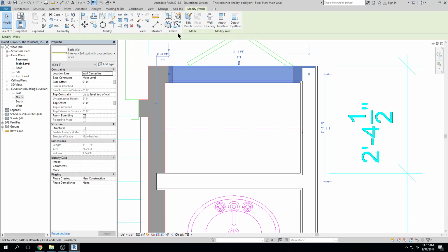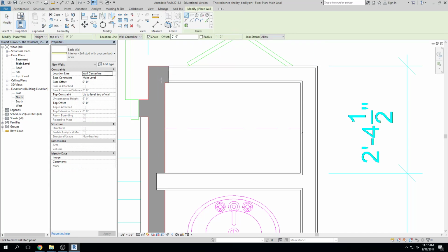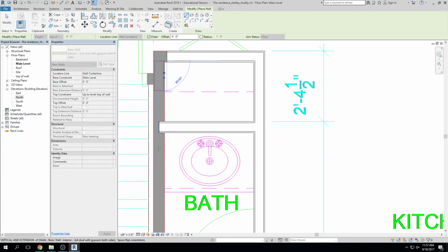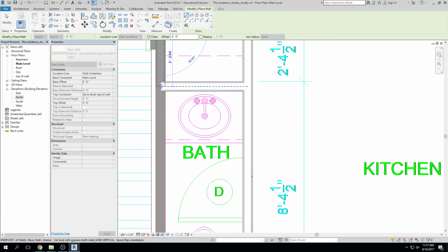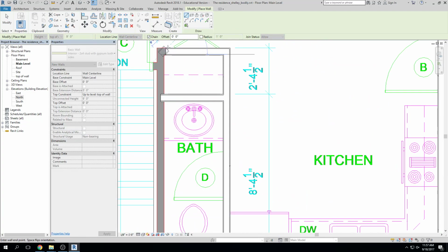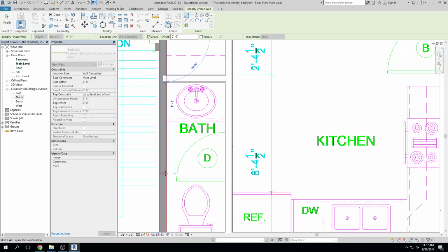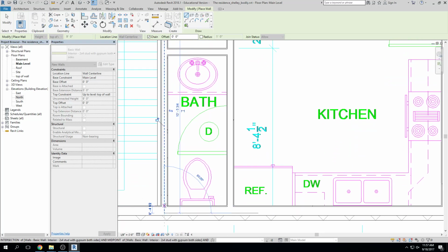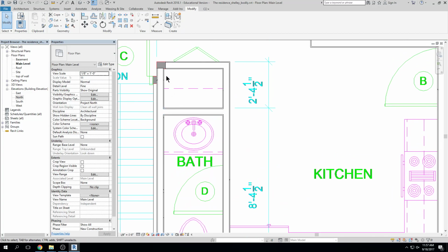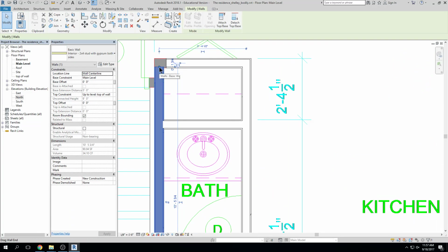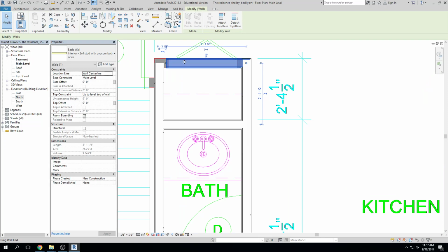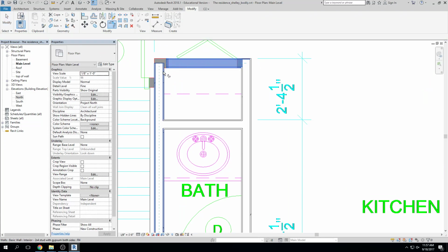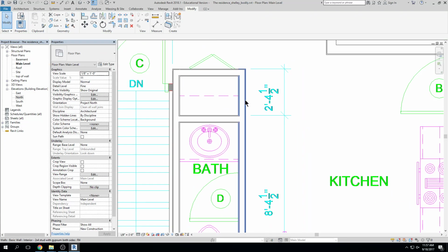Okay, click on my wall, create similar. Now I have to grab this wall and draw that. And you see, oh, it's going over the top of that one. It doesn't quite meet that one, right? We want everything to meet and be nice and tidy, but Revit is very easy to manipulate. I can drag that up, I can trim, TR, click, click, and things look pretty good.